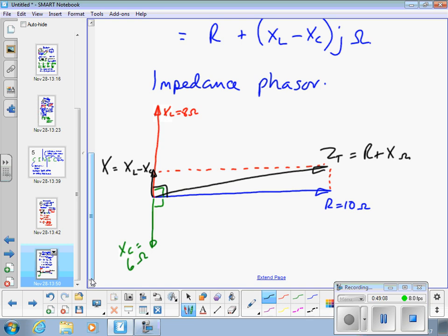Yeah, and we got our angle in there again. And the sketching of a phasor diagram is always useful so you can actually quickly get whether your angle is positive or negative from sketching out the phasor diagram and know in which direction this overall reactance needs to be.